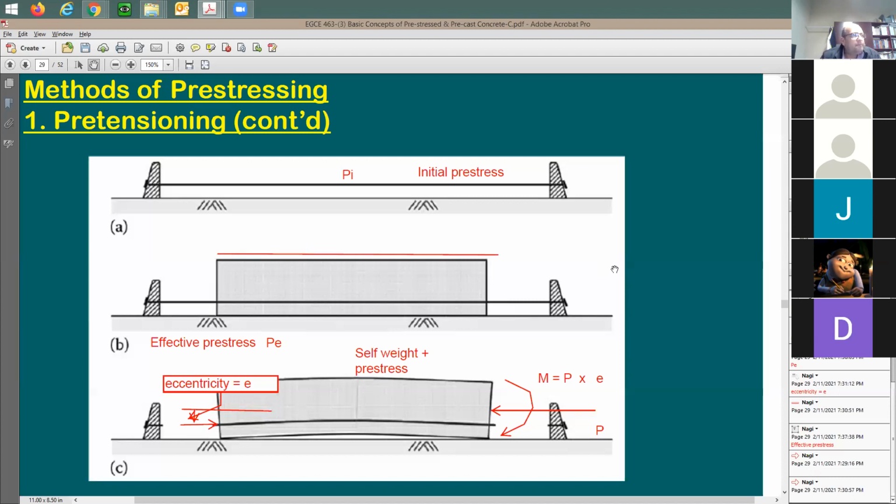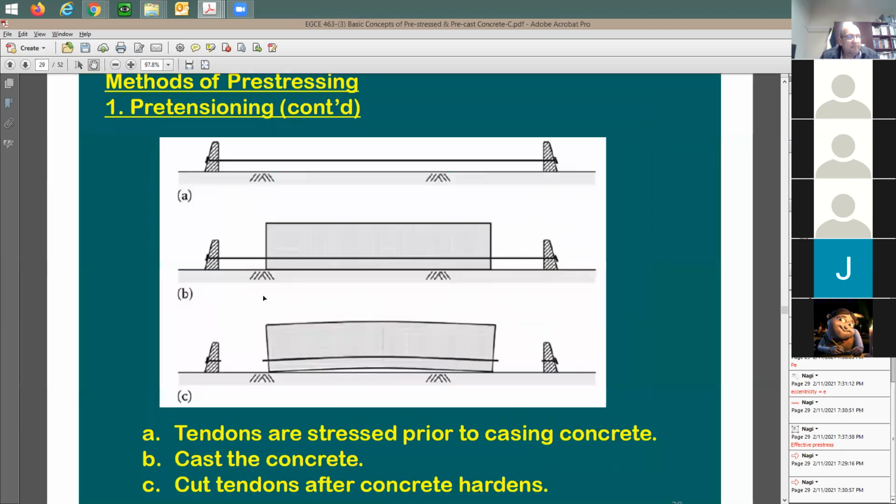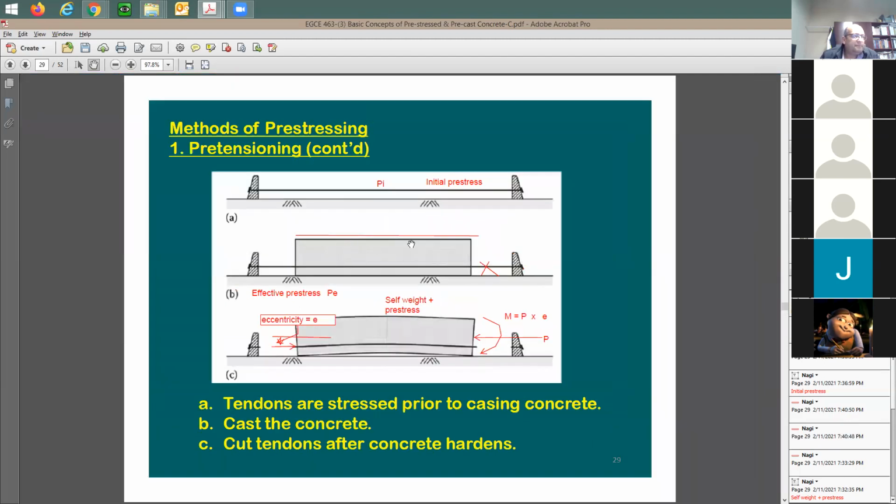I have a question, Professor. P, you said, is just the self-weight of the concrete here in this situation, right? P is this force. Did you see this? P is this force, right? Oh, I see. So we have a force there. The pre-stress force here is PI. You see what happened? First, you put this PI. And then once you trim this right at this point, the force is going to get transferred to the beam. Right here, the force is not at the beam yet. The beam doesn't see any pre-stress. But once you cut this, once you trim it, something you can do with a grinder, or you can just burn it if you want to, once you cut it from both sides, now the force is going to get transferred to the concrete. And they call this the transfer time. I didn't see that force. Now it makes sense. All right. Thank you. No problem.